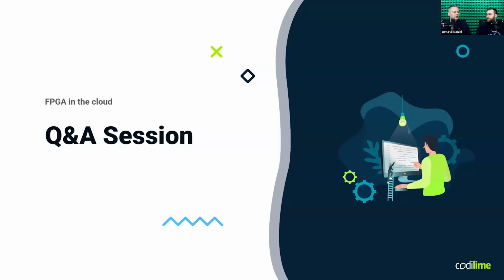Yeah, so currently our project is, let's say, single threaded. One packet comes, the processor analyzes it, and then sends back the response. Probably the question refers to whether we are able to process more packets simultaneously. This is an open item here. We checked that the FPGA should handle three instances of hBPF, so three multiple calls could be processed simultaneously.